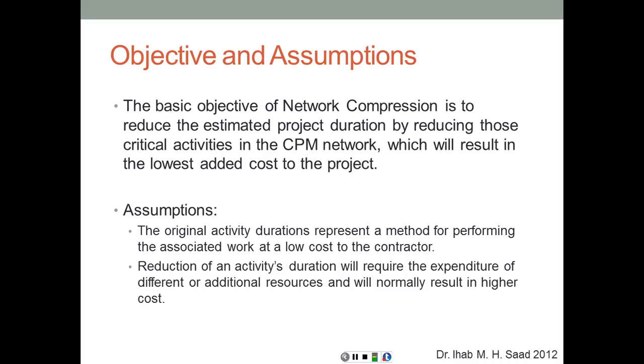Of course, the critical activities are the ones that control the duration of the project, so it would not be wise at all to compress a non-critical activity. It's not going to achieve anything. You'd be wasting your money, which will result in the lowest added cost of the project. So we're trying to compress the critical activities, resulting in the lowest additional cost for the project.